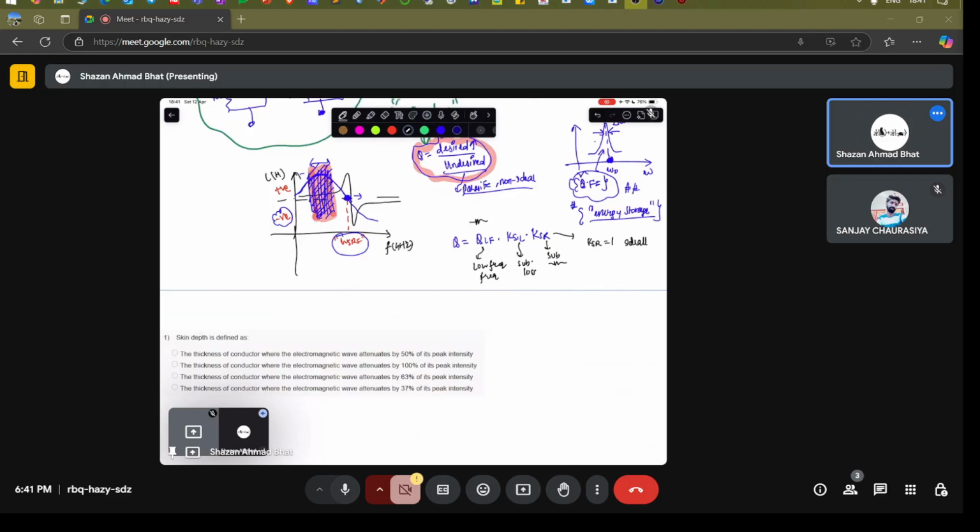This KSR should ideally be equivalent to 1. The values of KSR and KSL are less than or equal to 1 and greater than 0. If it is ideally 1, you want the quality factor to be huge. If KSR reduces, that means the substrate resistance loss is huge. Then there will be a leakage path of the currents towards the substrate, and that is going to be detrimental. That is going to make KSR, for example, 0.2, and that is directly going to affect the Q because Q will be reduced.